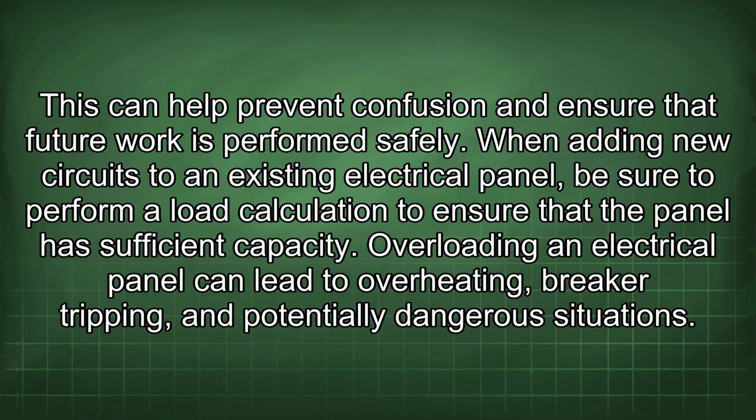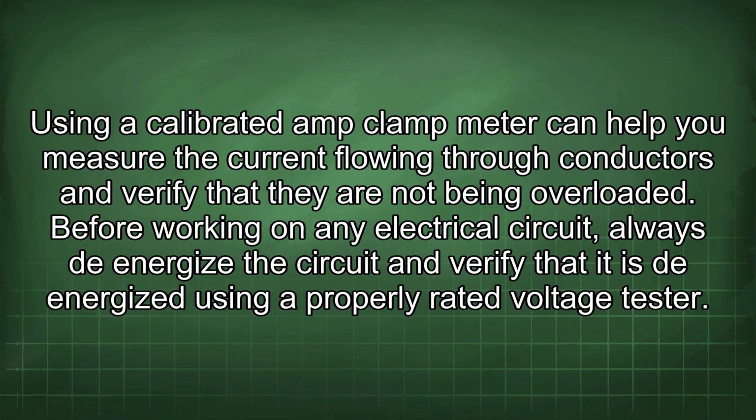When adding new circuits to an existing electrical panel, be sure to perform a load calculation to ensure that the panel has sufficient capacity. Overloading an electrical panel can lead to overheating, breaker tripping, and potentially dangerous situations. Using a calibrated amp clamp meter can help you measure the current flowing through conductors and verify that they are